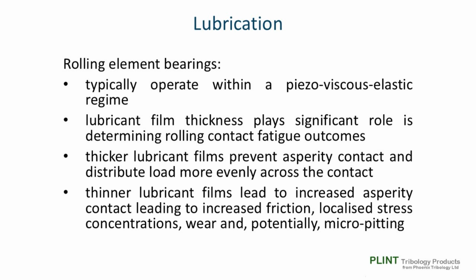Thinner lubricant films lead to an increase in asperity contact, leading to increased friction, localized stress concentrations, wear, and potentially micro-pitting.